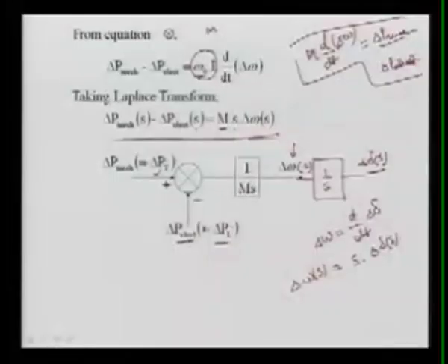So here I can write this omega S change as the change in the frequency if you are using the per unit system. If you are not using the per unit system, then omega is in radians per second and frequency is in hertz, both are different. We will see some problems on how we are going to relate it. Now we have to combine all these models. Models means the model of the governor, turbine and generator. Let us see what we are going to have.